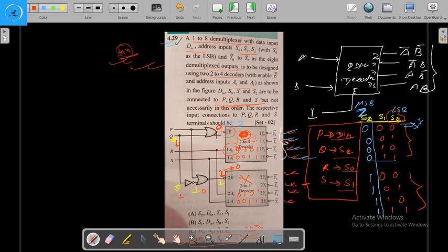From this point we have assumed that if we consider this as a signal Z, we can understand that this S2 is MSB. That's why if we keep this MSB 0 and change the rest as 00, 01, 10, 11, this decoder will work.